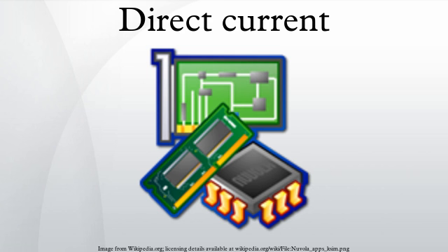This implies that the system of equations that represent a DC circuit do not involve integrals or derivatives with respect to time. If a capacitor or inductor is added to a DC circuit, the resulting circuit is not, strictly speaking, a DC circuit. However, most such circuits have a DC solution. This solution gives the circuit voltages and currents when the circuit is in DC steady state.